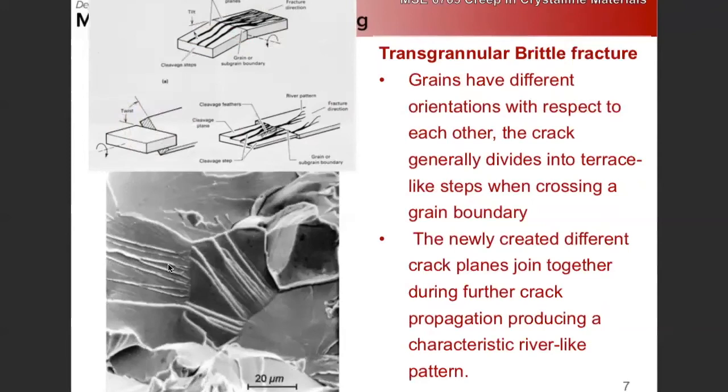Right? So essentially the crack's going to follow the path of the least surface area. So it's not going to take a tortuous route and make a whole bunch of turns. It can go relatively straight and follow 100 planes separated by little terraced regions that cut across from one 100 plane to another 100 plane.